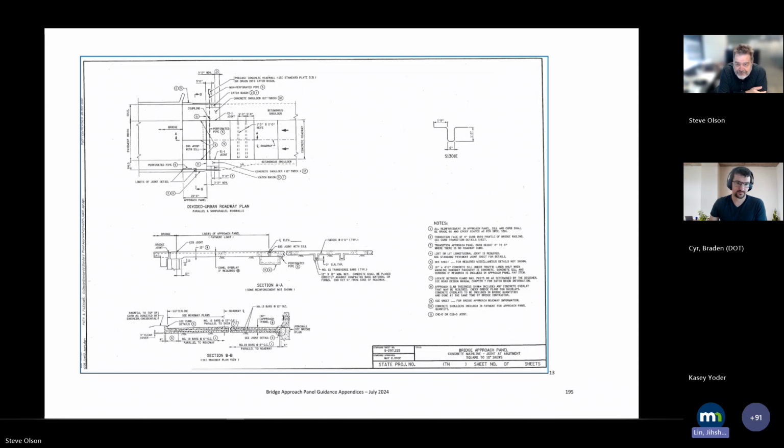Sorry, Paul, back to your question. It was for trying to reduce the friction and allow movement on integral and semi-integral abutment bridges. The concern we have is that if you take it out for parapet, it just doesn't translate through on construction. So we end up with no plastic on the bridges where we want it and plastic where we don't. I thought there might also be some benefit during rain events, to keep the rebar clean if it splashes up off the dirt, or whatnot. But the primary reason was for friction.